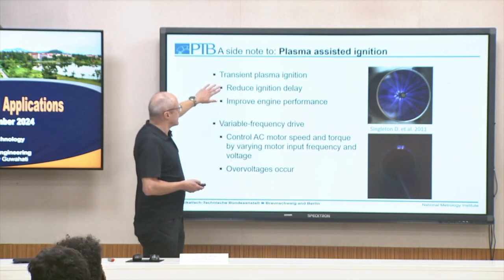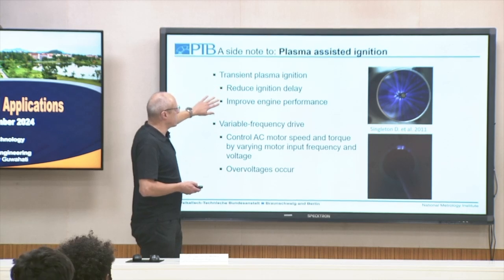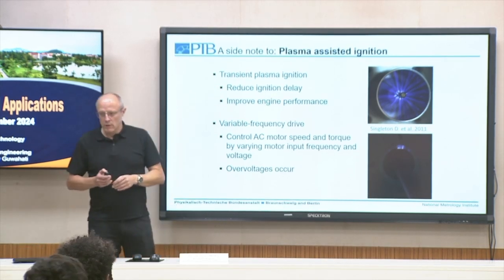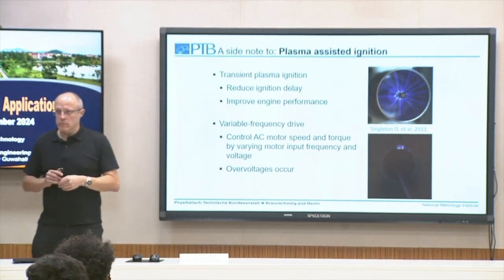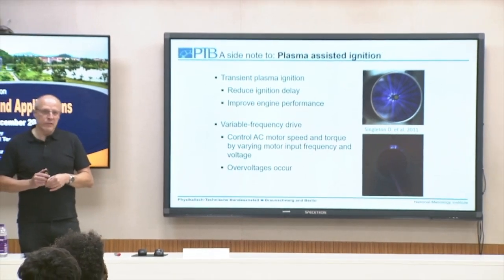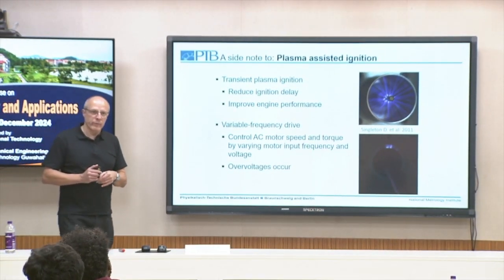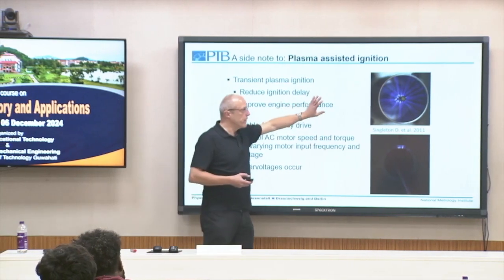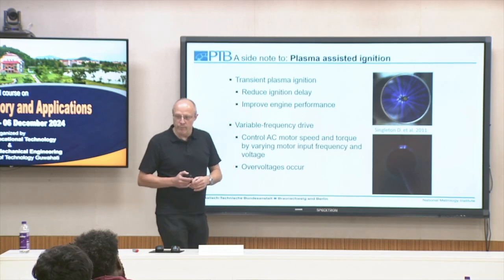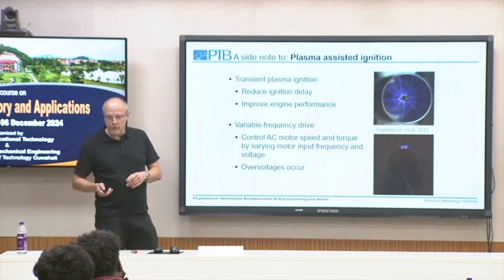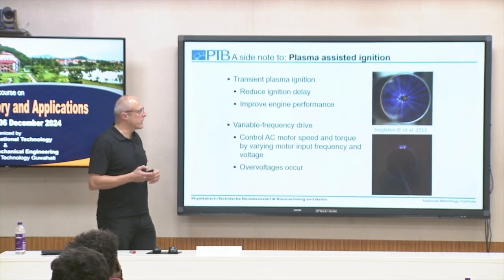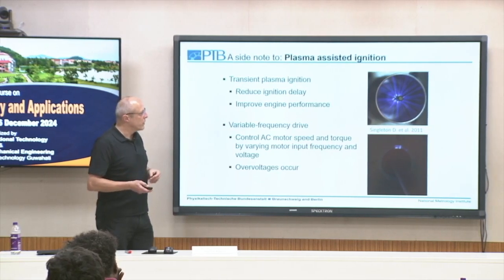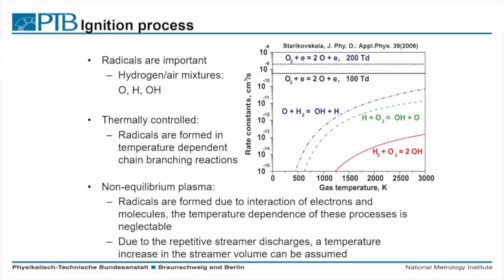So the idea is to have reduced ignition delay time, but of course especially to improve engine performance. There are also solutions now in the market where they use commercially available spark plugs where they use this effect. So this is one way to ignite a larger volume in your combustion chamber. But what we need to know when we use this so-called plasma-assisted ignition,